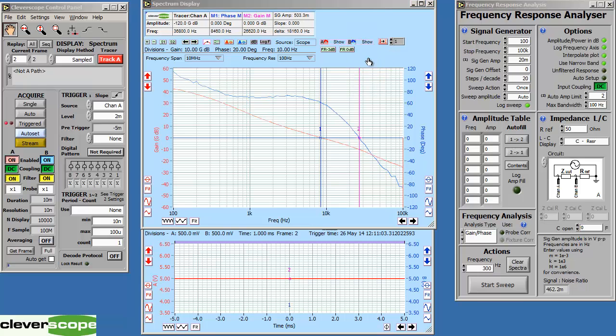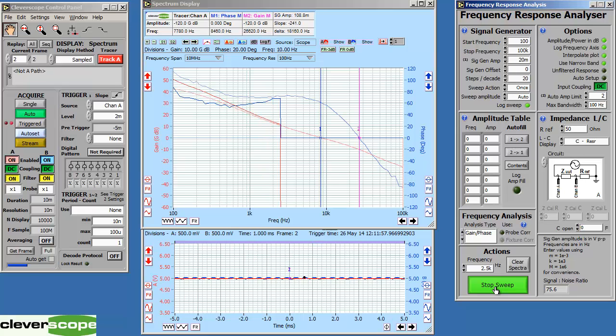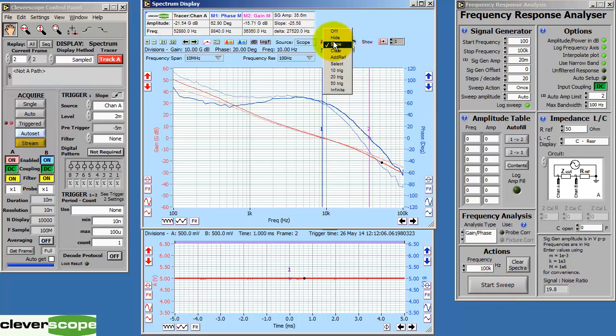Right, we've changed the load so it's just over an amp. Let's start another sweep. Again, we find the K factor and then start plotting gain and phase. The gain is slightly higher at low frequencies with the lower current. So we see the plots coming closer to each other as frequency increases. Okay, that's done. Let's add that as a reference as well.